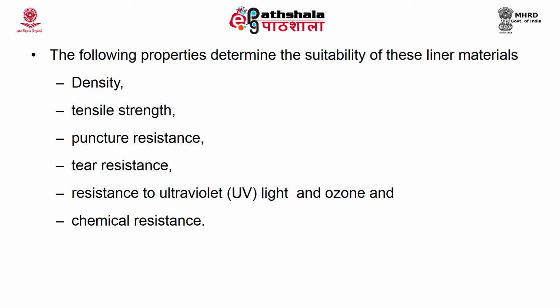Tensile strength means if you keep pulling the polymer, it should expand. To a certain level it should be flexible enough. Puncture resistant means even if there are some rock materials which are trying to tear it, it should not tear or be punctured by those materials. Then tear resistance, and since there are a lot of chemicals in this waste material, the flexible membrane should be resistant enough to these chemicals as well as UV light and ozone.